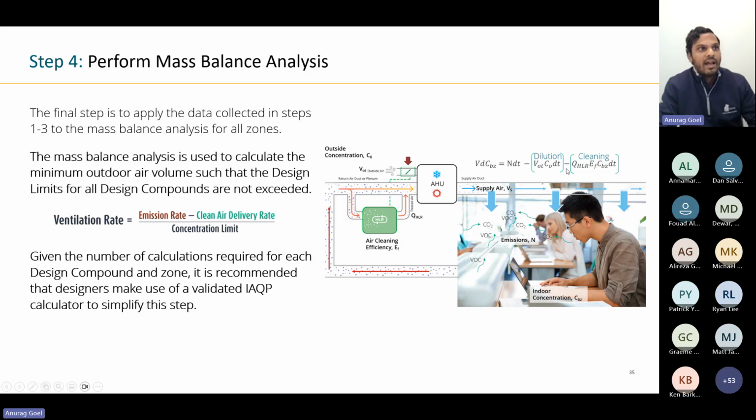So this is why the IAQP is a really clever design tool: it has two unknowns, outdoor air and air cleaning. You can find the right combination of these two unknowns to achieve project goals related to load reduction and energy efficiency. An example of optimizing around load reduction could be that maybe in your building, I have a total prescriptive exhaust requirement of X CFM from all the bathrooms in the space.